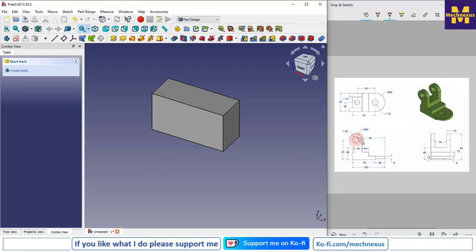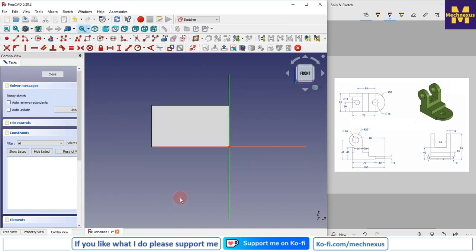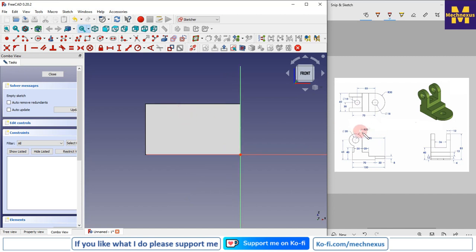And now we will remove the material on this profile. Here we will completely remove the material. So for this I will select this face and create a sketch, and for the sketch we will draw this diameter of 40. Here is R20. So I will select a circle and give it a